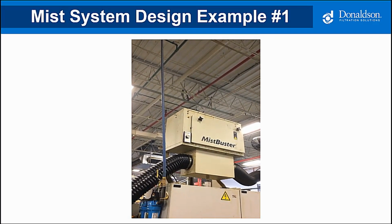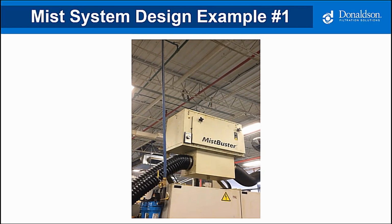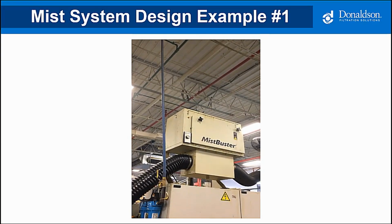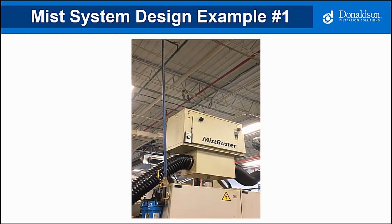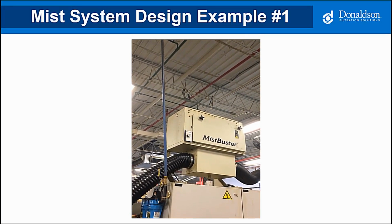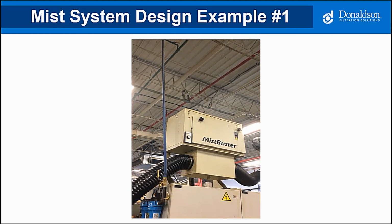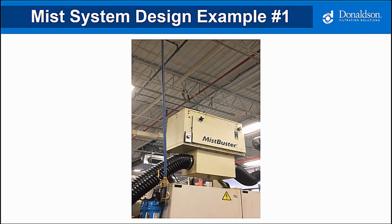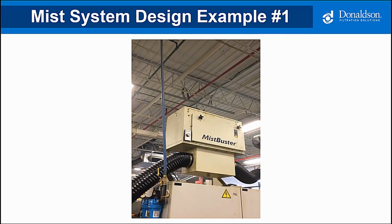There's several reasons why this might be happening. Most likely it's due to poor maintenance. As you remember from John's previous slide, electrostatic precipitators use plates, and when those plates get dirty, the mist and smoke is going to bypass. There's some other things that can possibly be going wrong in this situation. You might be using the wrong filtration technology, again, causing the plates to plug up quickly, or possibly the system's undersized.